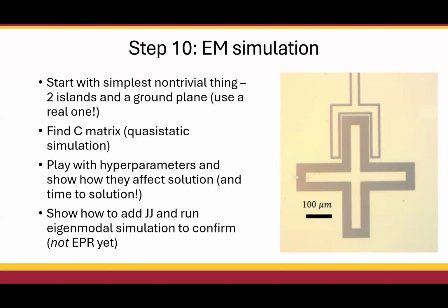So now that we have Pallas running, cluster is going to come in. If your institution has a spare few $100,000, you can run HFSS on the cluster. Ours apparently does not. All right, so at this point, now I would add in the Josephson junction, show them how to do that in the simulation, which Murat's going to show later, and run an eigenmodal simulation and show that you actually get a resonant frequency, and have them compare with what they would calculate from their electrostatic simulation, from their capacitance matrix, with just writing down the inductance of the Josephson junction.